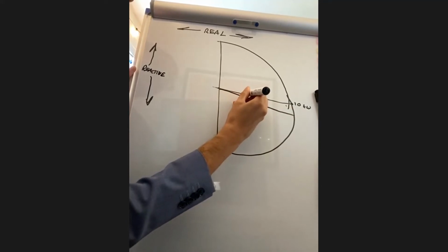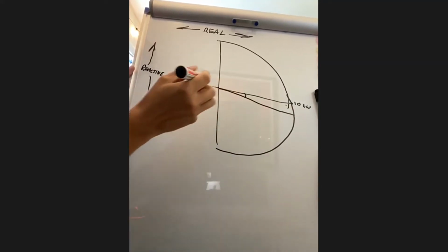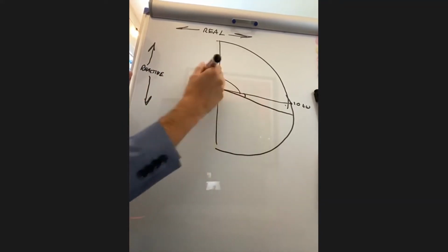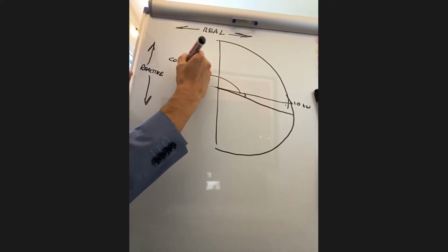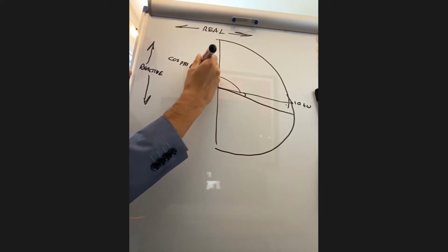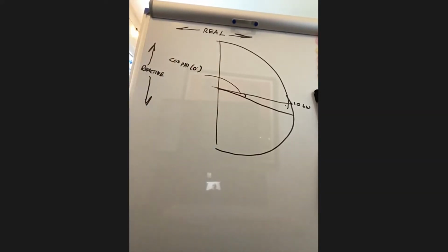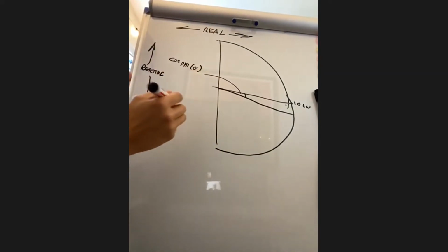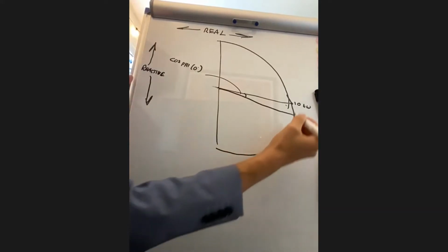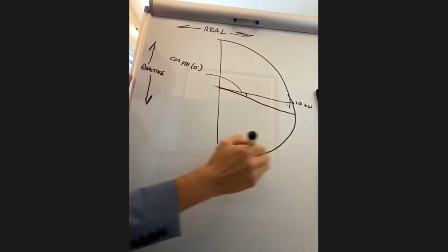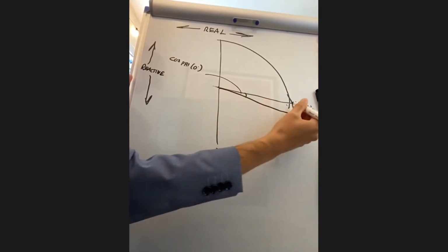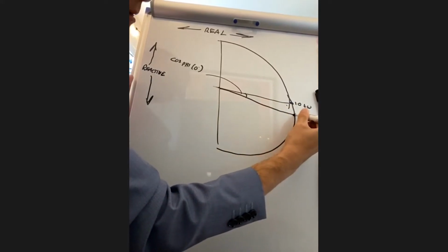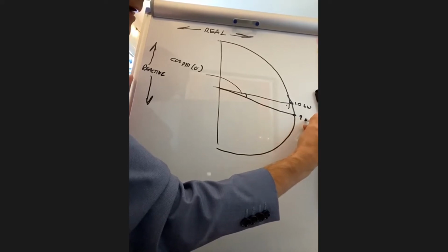And so when people talk about power factor, oftentimes they refer to the cos phi angle, the cosine of phi. And this angle here is phi. So you have the cos of phi and then some number of degrees in there. And it's interesting because I used the example of 44% earlier. So essentially what's happening here is you've gone down on this curve a little bit, which means you've backed off of the absolute maximum amount of power that a smart inverter can produce. So you're no longer producing 10 kilowatts, but let's say in this example, you are producing 9 kilowatts.